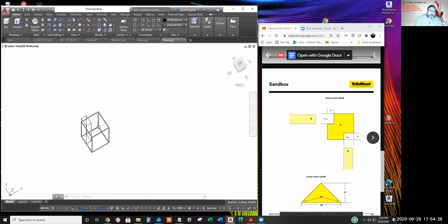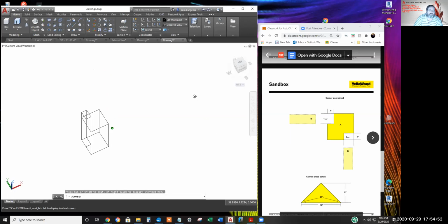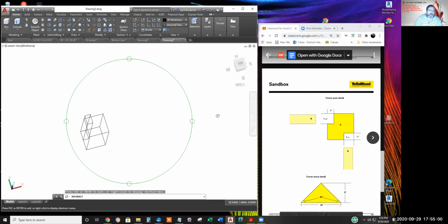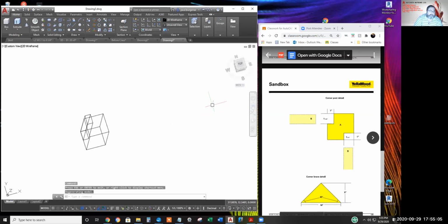If I make a mirror line from either of these 2 corners, hit escape, about a 45-degree line. Now, in this perspective, a 45-degree line is very close to straight up the Z-axis. So I'm going to tweak my view a little bit so that the Z-axis won't be confused with the 45-degree polar tracking increment.